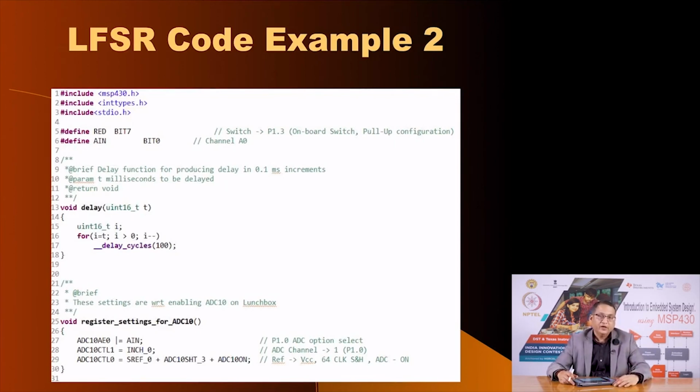What would you expect? You would expect that the LED will be on and off, but whether it is on or off, or for how much time it is on or off, will be pretty random. So what you would notice is that the LED appears to flicker. This would be a good way to create a candle-like performance on an LED; it would appear like a flickering candle. So if you compile and download this second code example and run it, you would see that the LED which is connected to port 1.7 is flickering at a random rate and it would appear like a candle.